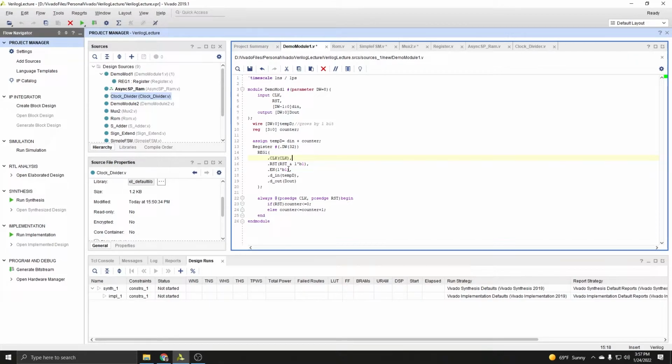So you just have one register with the enable, and then you put a constant value signal to that enable, or whatever control signal it is, to then allow you to have basically a constantly enabled module. So you don't need to worry about the enable switch. Just give it whatever constant value will not interfere with the normal operation of your module.